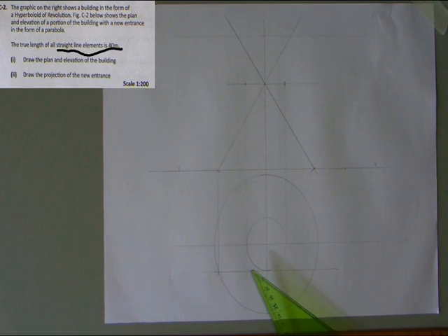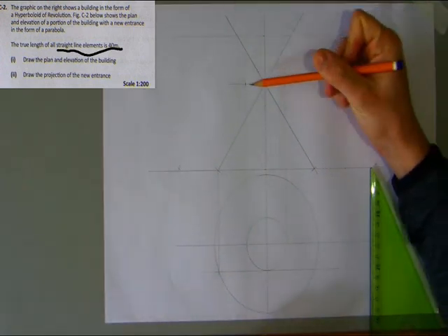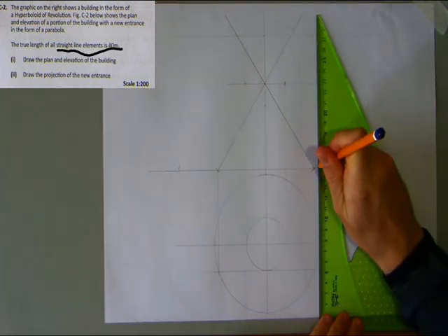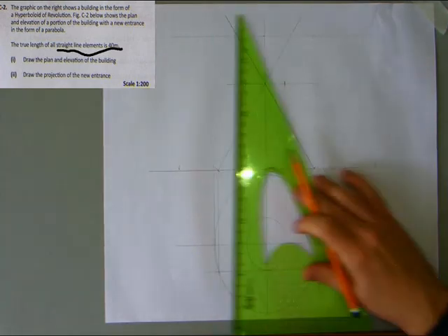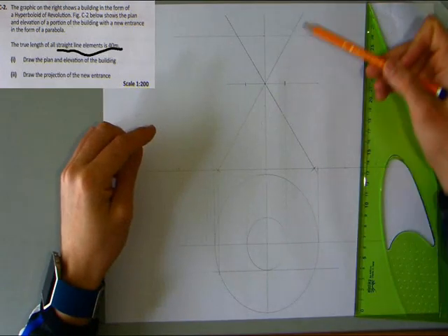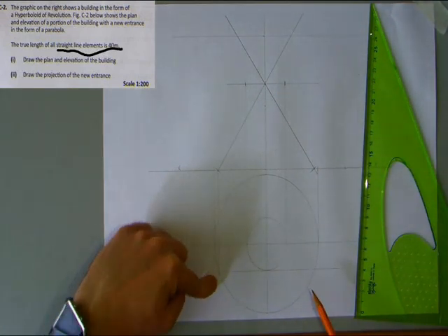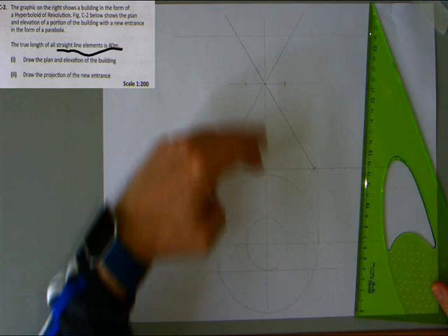Okay, so we now have our throat circle, our base circle, which is there. We have our asymptote, or at least the bottom half of the asymptote. We have our cut here, which is creating the asymptotes, or our straight line elements, and then we're going to create the hyperbola on either side.